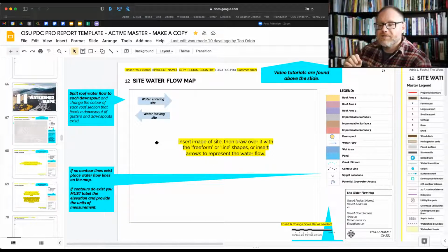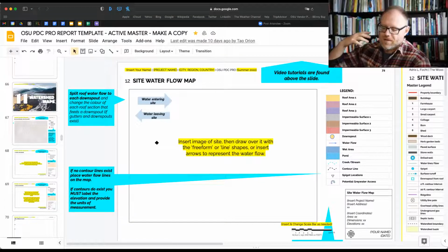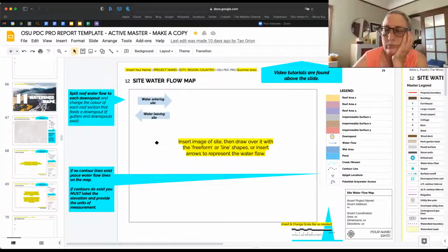So if we take information from these sources I'm just about to tell you, we have to take them with a grain of salt, and we'll have to ground truth everything on site. And this is what we have to do regardless. So if I make a plan, even with sub 8 centimeter topographic information, if I go and lay out an alleyway cropping system or an orchard or whatever, I'm still going to go and lay that out in real time and use a GPS and find my points and all the rest of it. So I'm still going to get to accuracy that way.